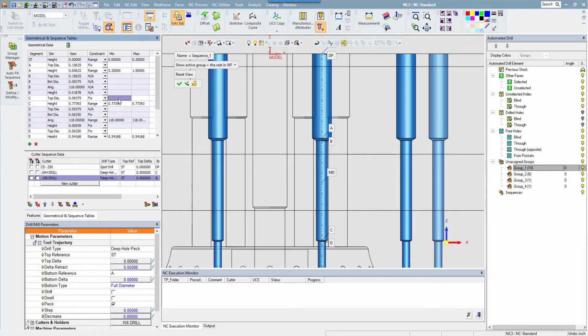We're going to leave that on fixed again because that's a diameter that matters. We need that. Now, if you have a customer, let's say your design is outside of Cimatron, you're bringing in files from another software, this might not be a good option for you if you ever have a problem with data. So maybe your diameter range would be plus or minus half a thousandths. That's an option and it would allow it to work if you had a slight variation. Now, is it a great option? I'm not sure. I think I'd rather have it fixed, but if you need that, it's there. So we're going to go back to fixed.